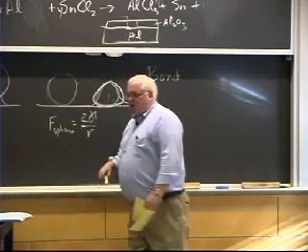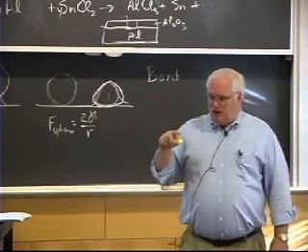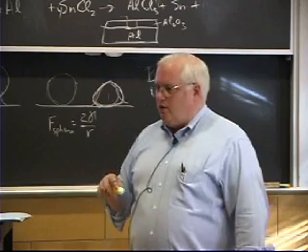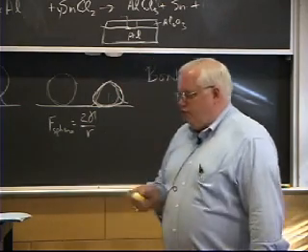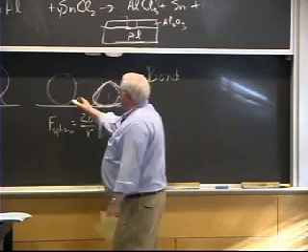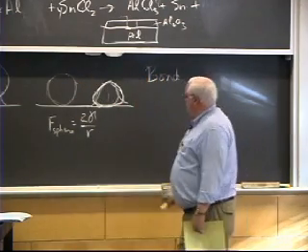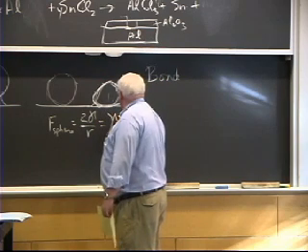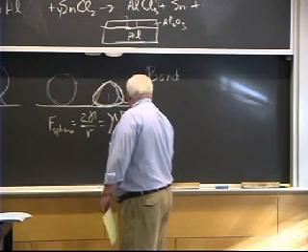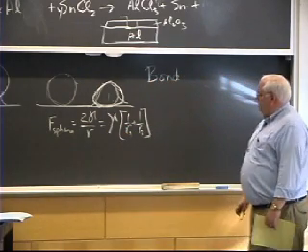It's gamma times the curvature we talked about before. For a sphere, the curvature is 1 over r plus 1 over r. It's the 2 principal radii of curvature, and for a sphere they are both equal, because the radius in both directions, around the equator and around the poles, is r. So that's gamma times (1/r1 + 1/r2), and in this case r1 and r2 are equal, so it's 2 gamma over r.